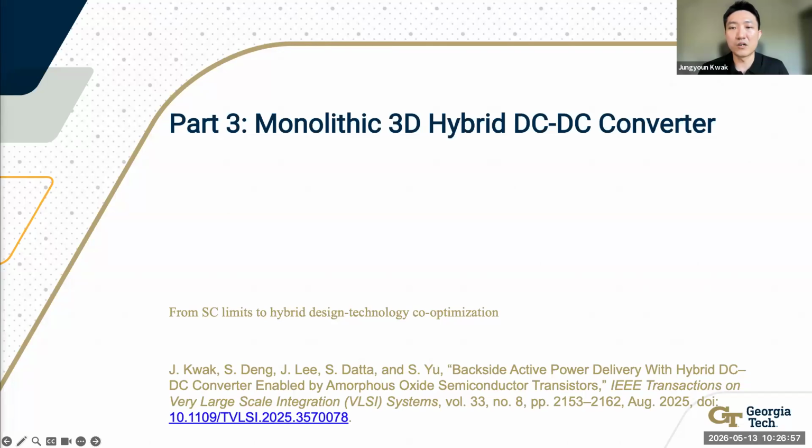In our design, a buck converter steps down from 12 volts to 1.5 volts, then a single switched capacitor stage takes 1.5 to 0.75 volts. The buck duty cycle handles fine-grain regulation to hit the nominal operating voltage.